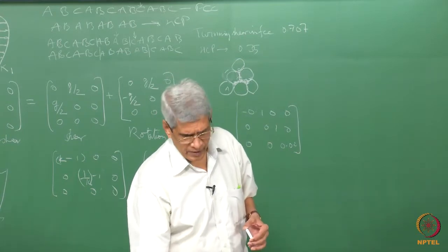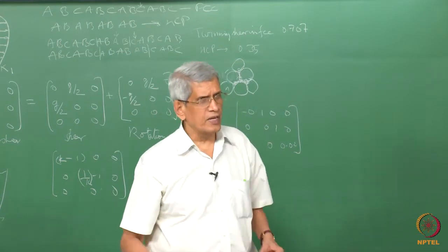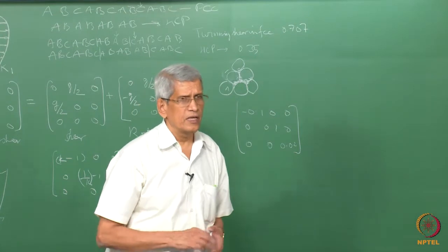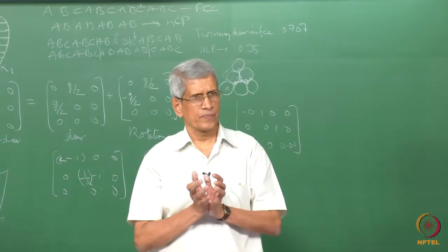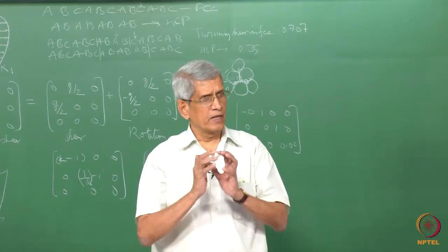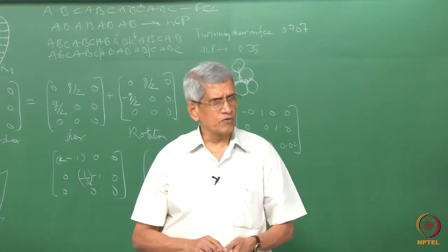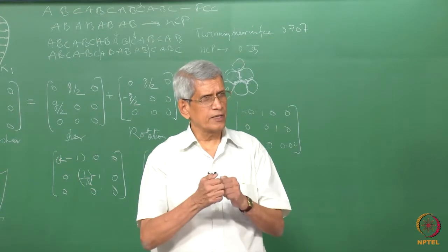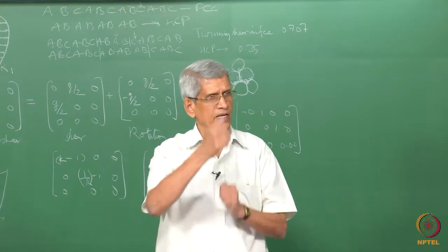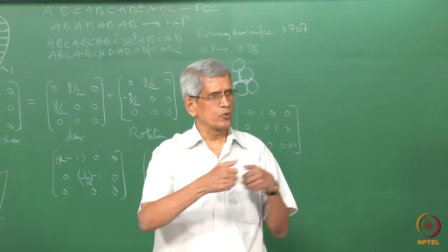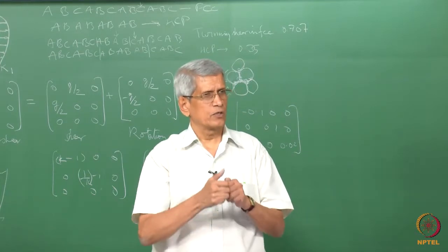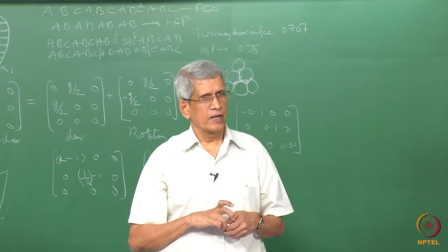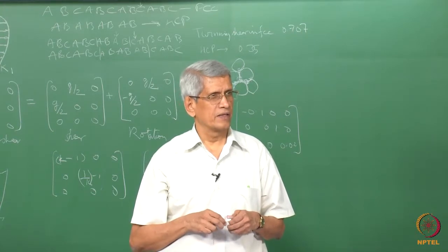Suppose we take a portion of a sample which is a sphere, with the orientations which we have chosen, and then give the respective elongations, 10% in two directions and 2% in the other direction, so that it has become an ellipsoid, correct?